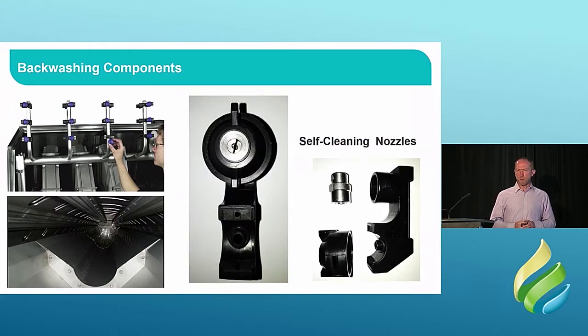Something we did about 5 years ago now was introduce self-cleaning nozzles. So it's always good to get operator feedback, and something we were hearing is that those nozzles were blocking, and it was a bit of an O&M task to have to get in there and unblock the nozzles with a toothpick, typically, about a 1 millimeter jet on the nozzles. So it was something that took some time.